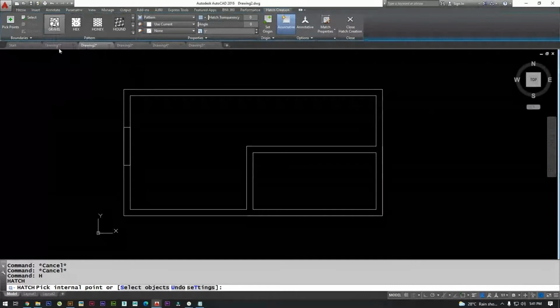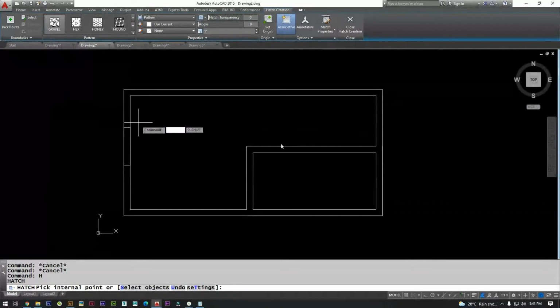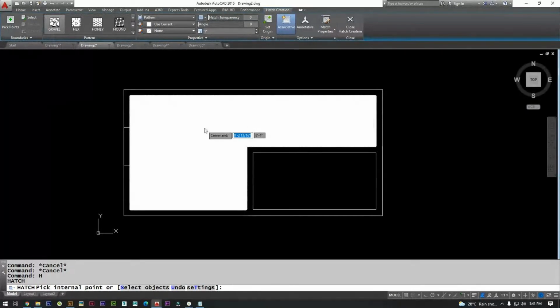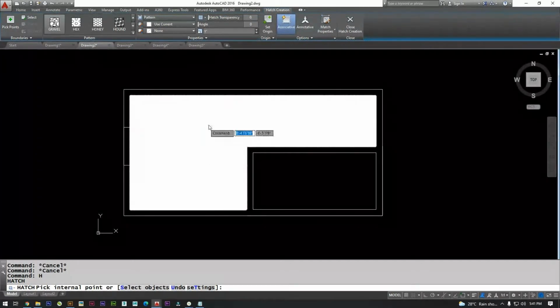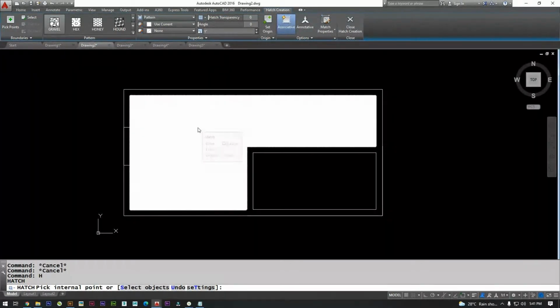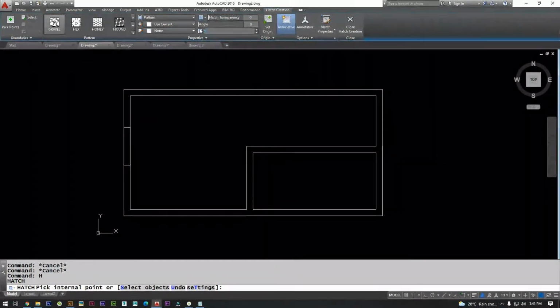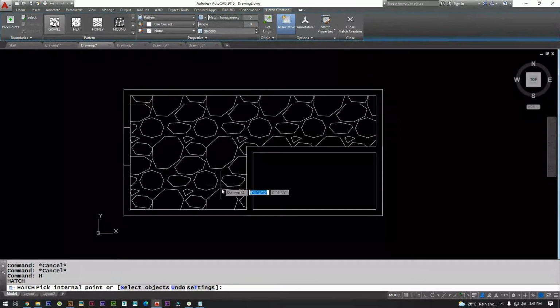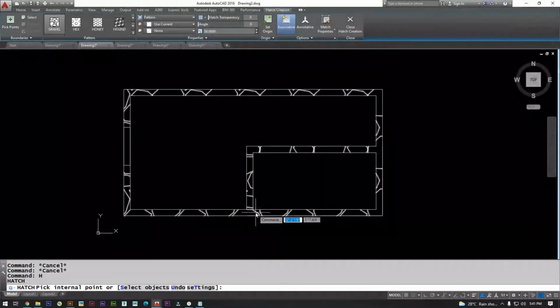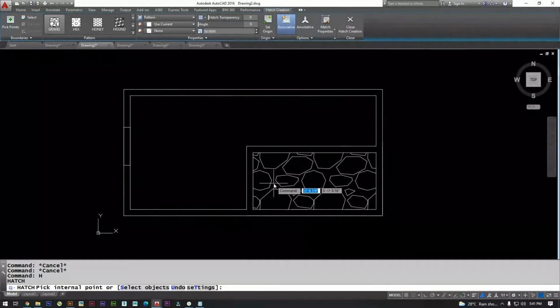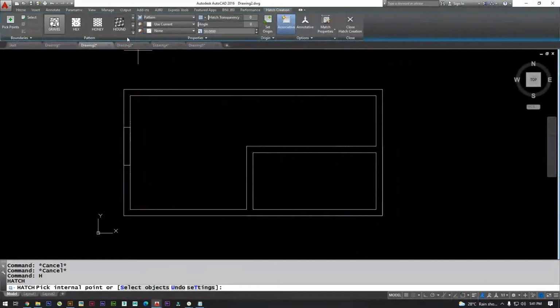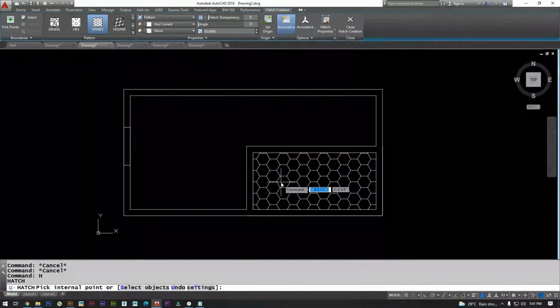And if I place this, it's looking like this. So here you have a scale value. I have 1 there, I'll make it 50. I just check, you can see. I can clearly hatch it to anything. If I take this, just click, hatching is done.